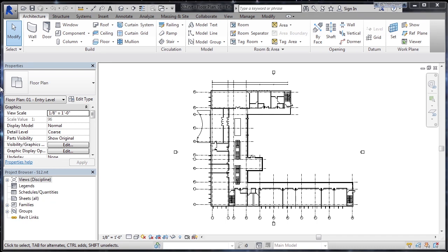And what you would really like to do is coordinate those into this Revit file, so the Revit file acts as the central host to these CAD files. So they can actually be monitored, what's been changed, what's not, and then I can actually see these instead of a flat 2D view in a 3D perspective view. To illustrate that, we'll look at the model I have on the screen. Right now it looks like a flat 2D drawing, which it is.